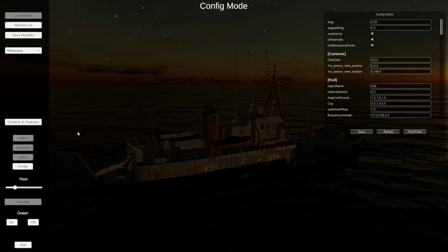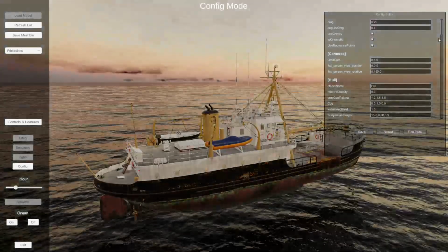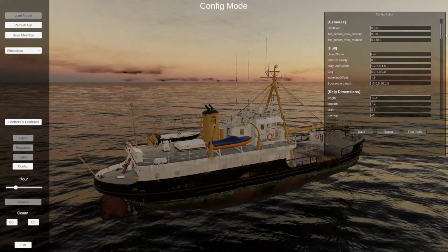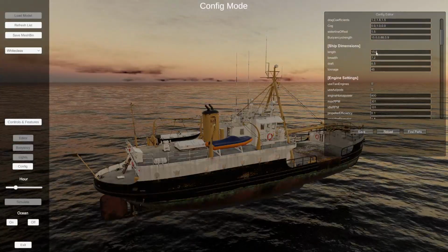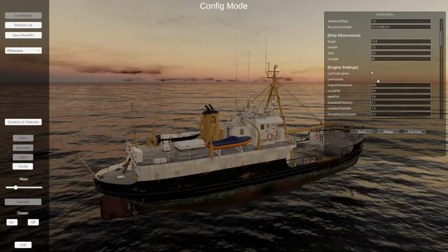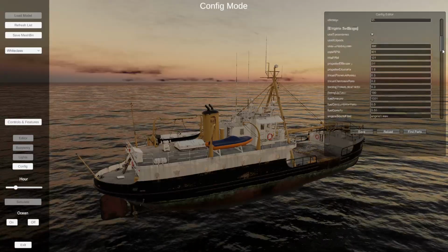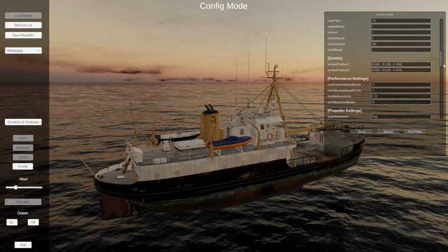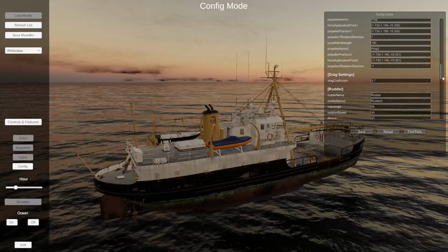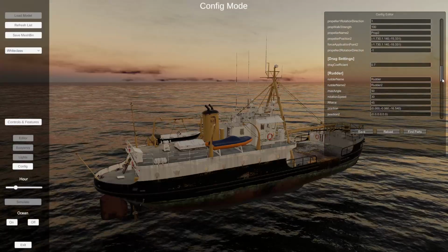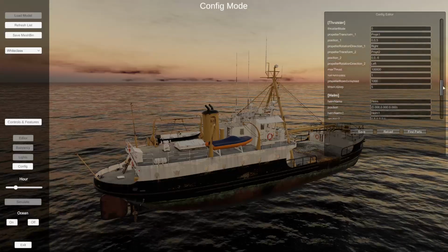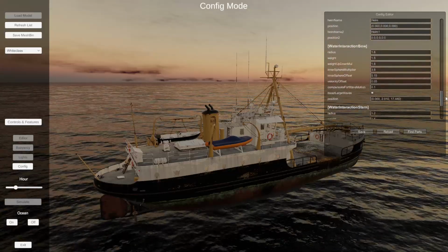And then in the CFG, you're going to put all your parameters as you usually would. Right, ship length, beam, draft. I've got 2 engines in this case. Then all your engine parameters. Smoke's already done in the editor. Propeller's done in the editor. The rudder's done in the editor. You can add your thrusters. Your helm will be done there as well.